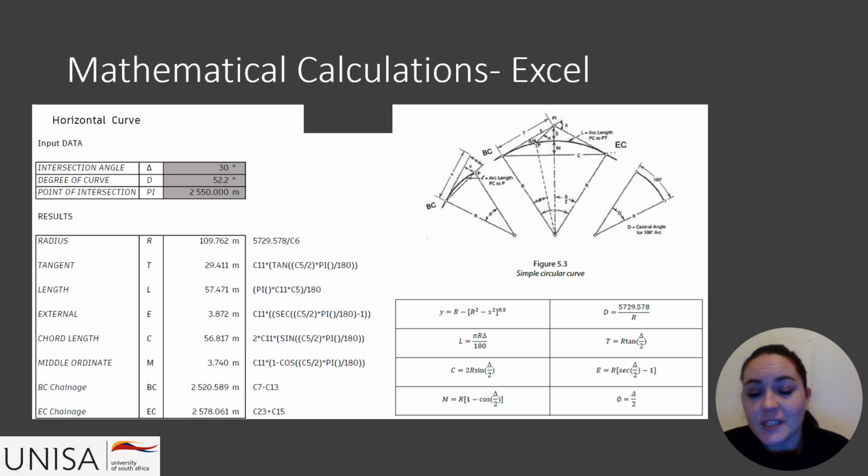This is when I noticed that the design is incorrect and that the roads I've chosen fall out of the scope of the project, as I chose 2 roads that intersect instead of one long road. The design criteria is in fact incorrect, because the speeds to stop and start at that intersection would change, which would then adjust the curves and the radius.